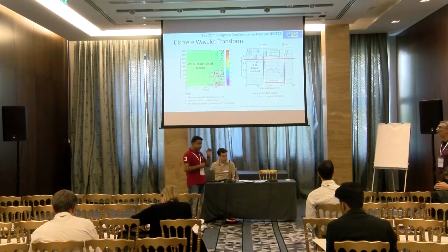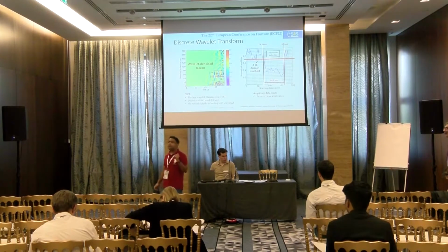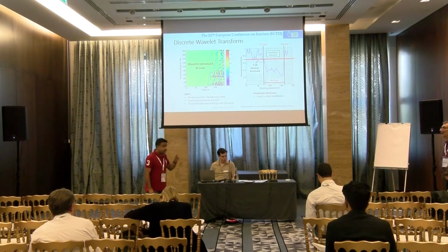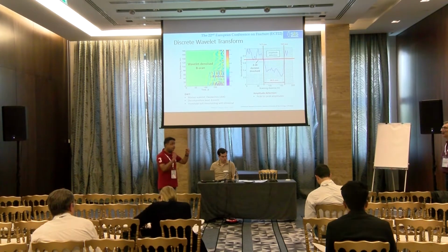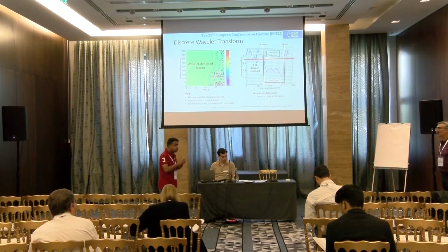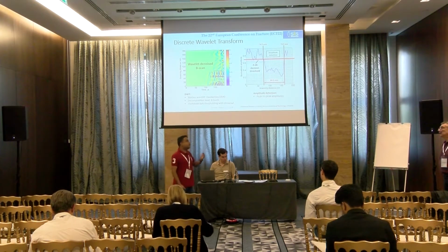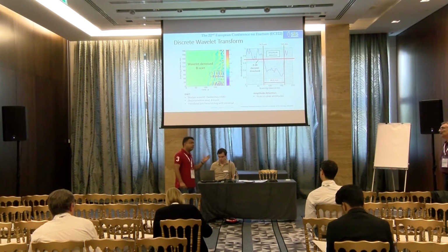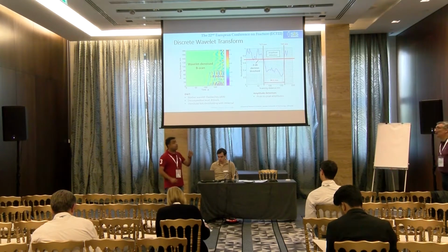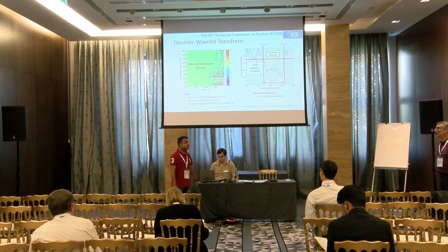Yes. The limitation of linear ultrasonic testing is the size of the defect. The size of defect that we can measure depends on the operating wavelength. If the defect size is less than lambda by 4, we cannot estimate it by this technique. For this purpose, there is non-linear ultrasonic testing combined with the peridynamic theory. I am not working on that, my colleagues are, but we can estimate the cracks also, from the peridynamic theory, but it is still not validated by experiment, only by modeling.